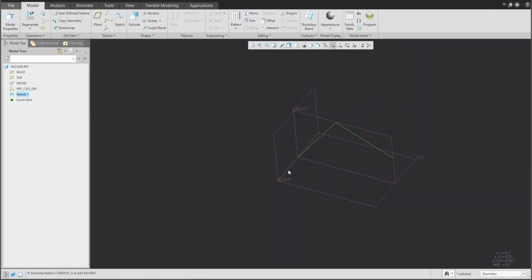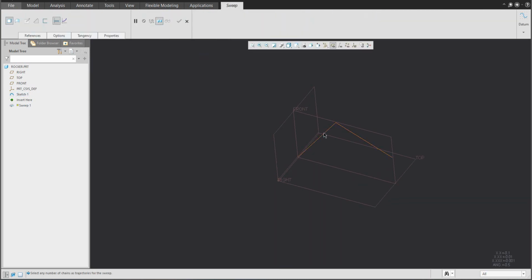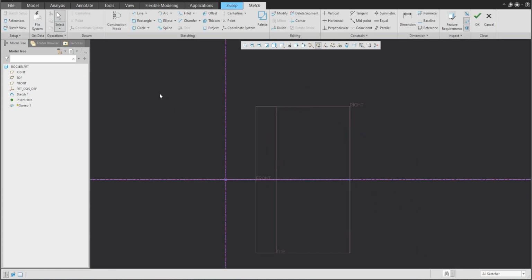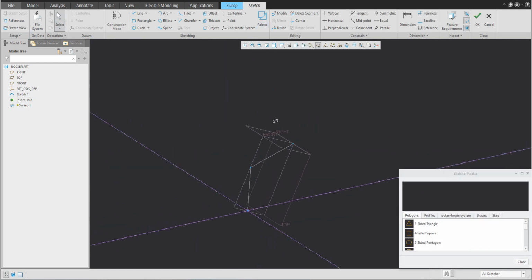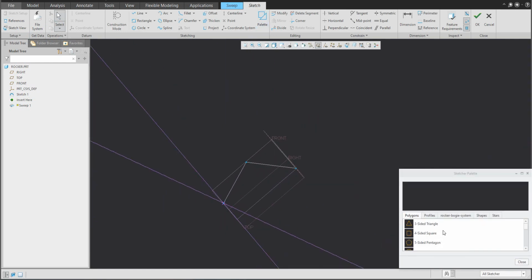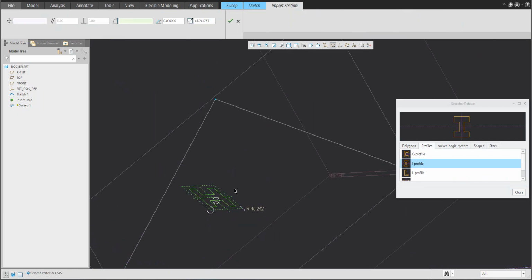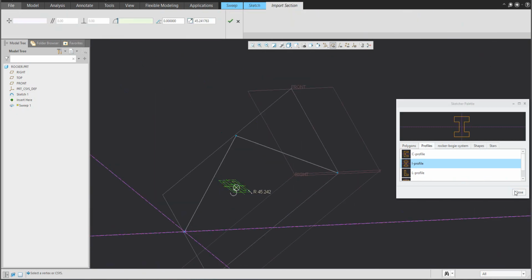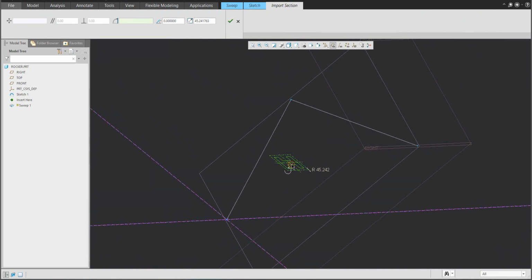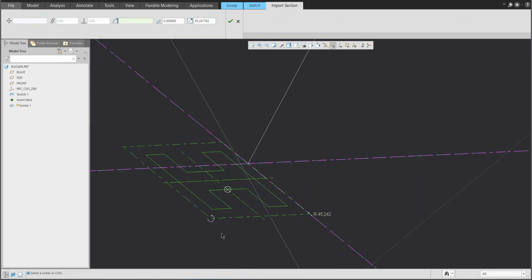And for example I would like to use only the sweep feature over here, and with the specification of the shape, we can select for example from the sketch palette, and you can choose the custom profile. So it's only for your explanation that it's not necessary to always define the custom sketch line by line, but you can orient it.